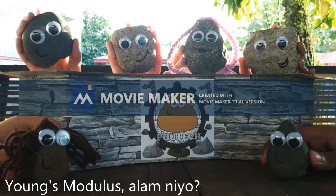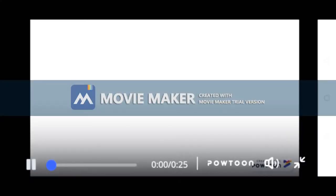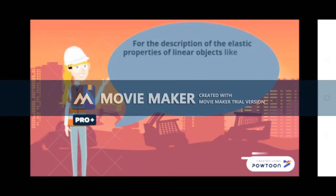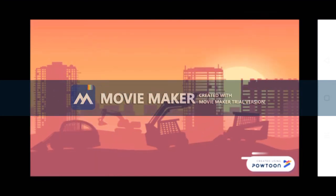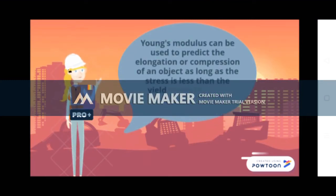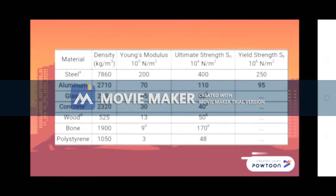Young's modulus. The description of the elastic properties of linear objects like wires, rods, columns which are either stretched or compressed. A convenient parameter is the ratio of the stress to the strain, a parameter called the Young's modulus of the material. Young's modulus can be used to predict the elongation or compression of an object as long as the stress is less than the yield strength of the material.